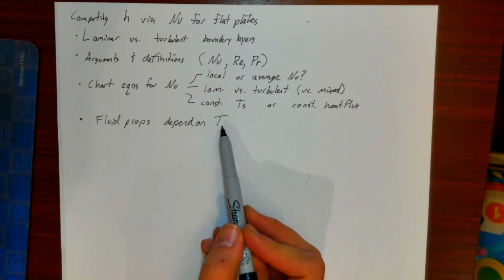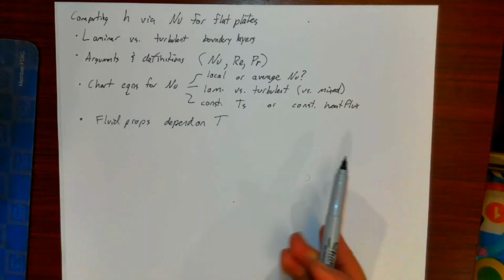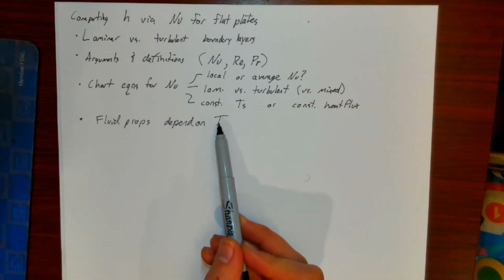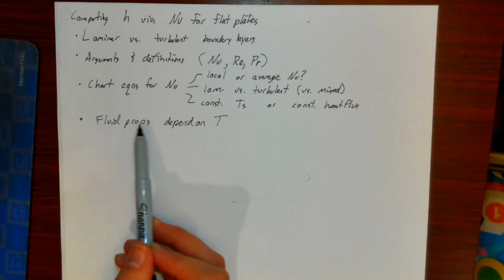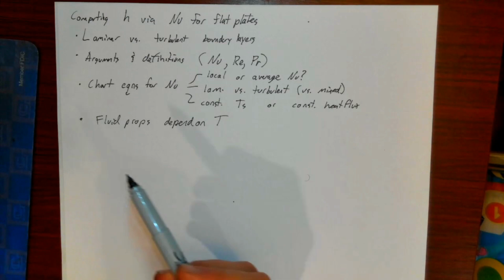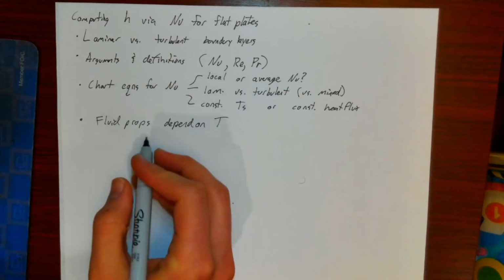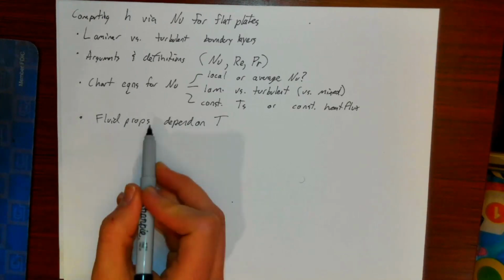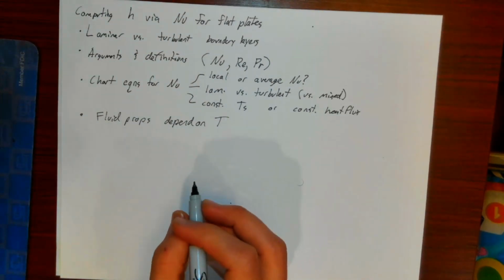We're going to have a different temperature for the fluid close to the surface versus far away, upstream versus downstream. Strictly speaking, there's not one single temperature that applies to all of this fluid, so these fluid properties are non-homogeneous over the whole system. So can we describe a single set of fluid properties so we can actually go ahead and use these correlations?